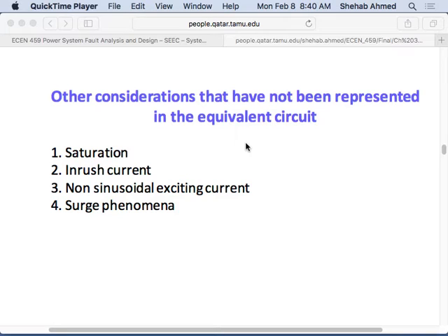Why? We will see later, because again, this is going to be part of our single-phase equivalent circuit. It's an impedance in our single-phase equivalent circuit. If it's too much impedance, too much reactive power that's going to be required to do this transformer action, I don't want it, right? So it's a component, something in our circuit that we need to account for. It cannot have more impedance than we expect or less impedance than we expect. It should be exactly what we expect.